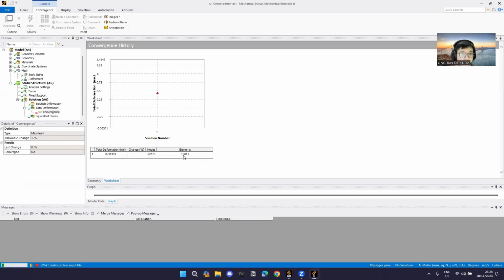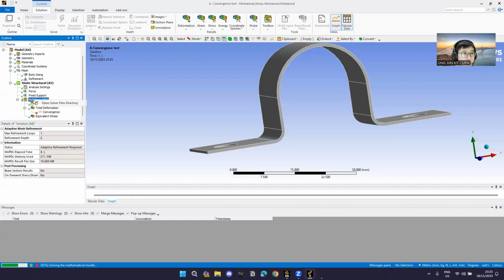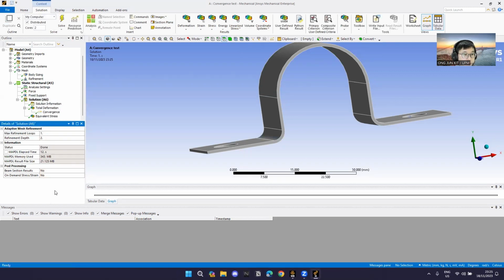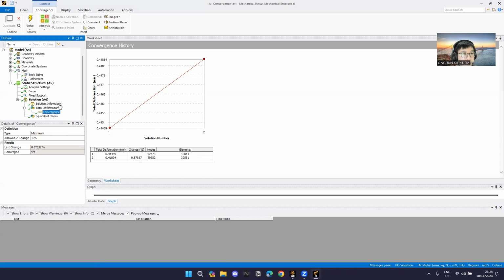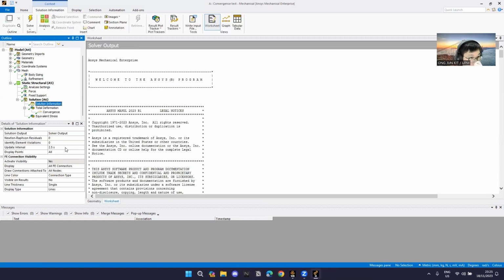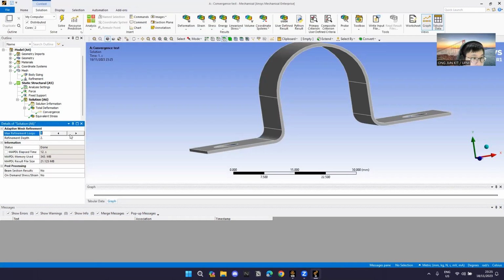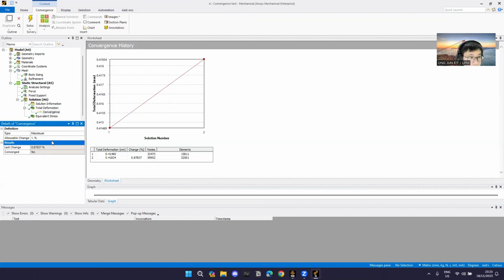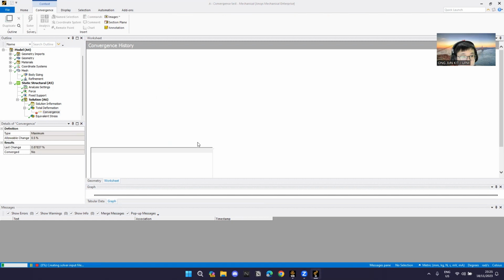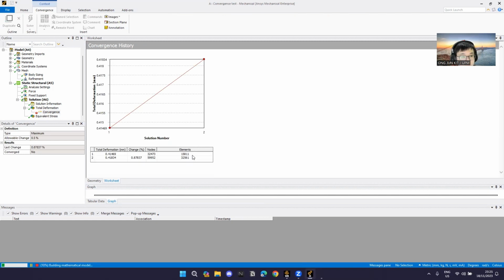Now our element count is 15811. We see the iteration loop first. We already looped one time, so maybe later we loop several times. It is 0.8%, so maybe loop some more times. Maybe we change this to 0.5%.